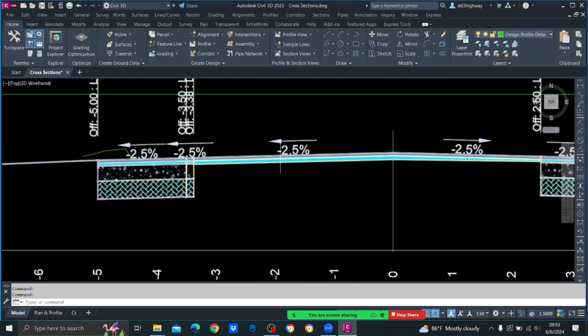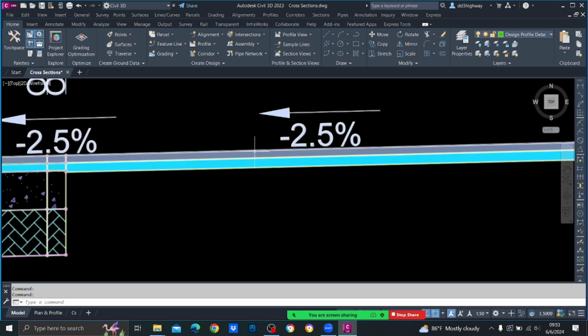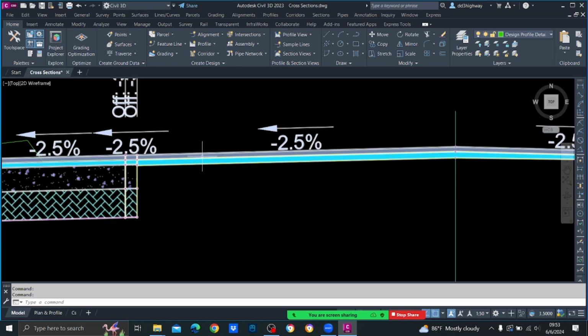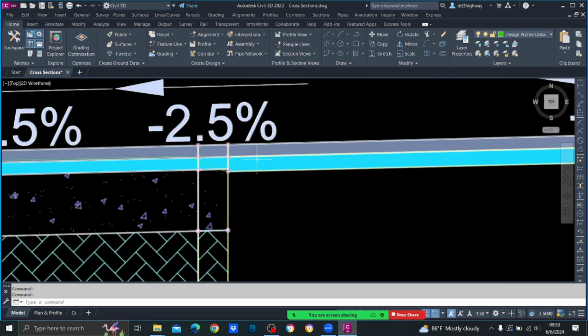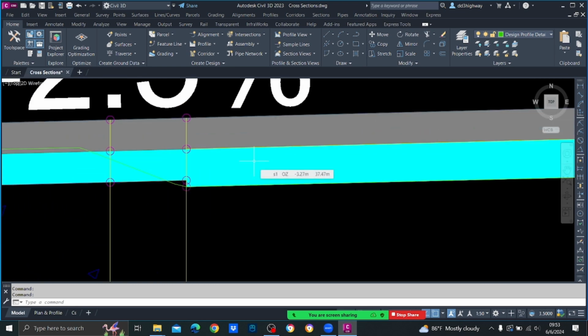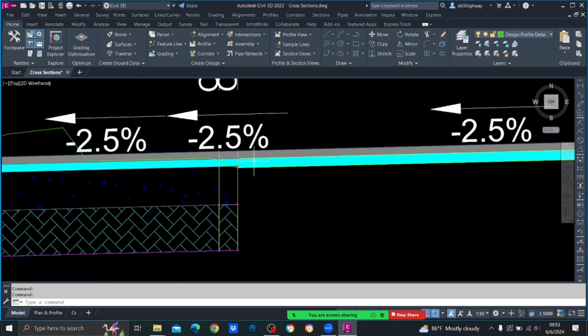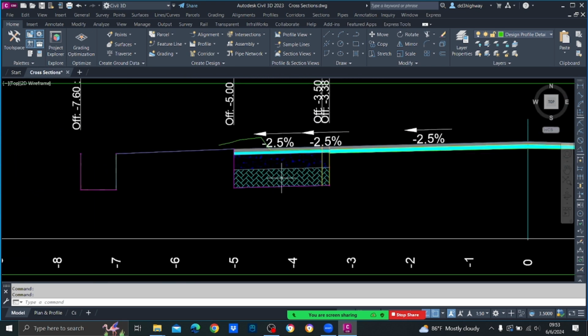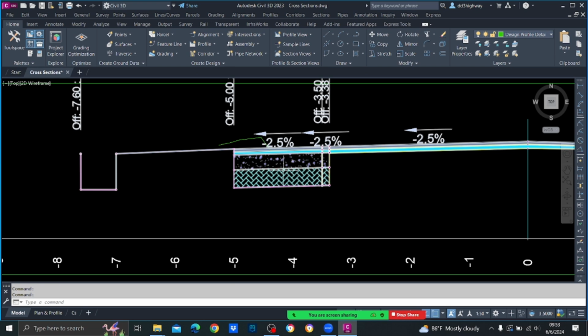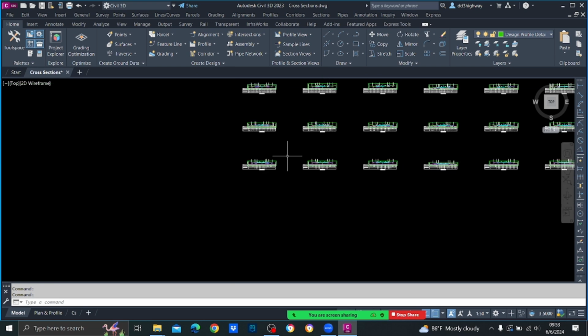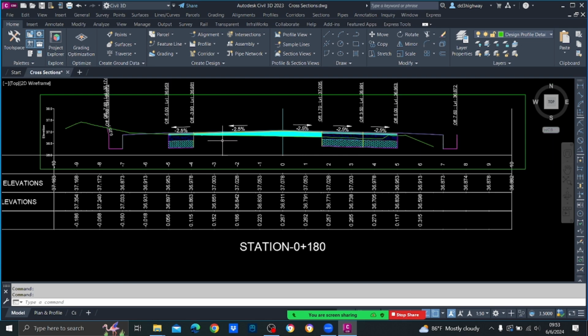If you consider this cross section, you know what this topmost layer is? That is the wearing course, and underneath that you have the binder course. Then for the filling sections you have ABC, and here you have soil type 1 soil. And if you consider a location like this, you can see there is some cutting and filling in all. So we can calculate all these things.